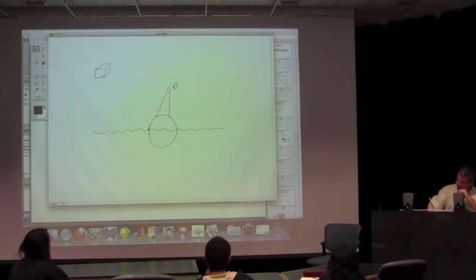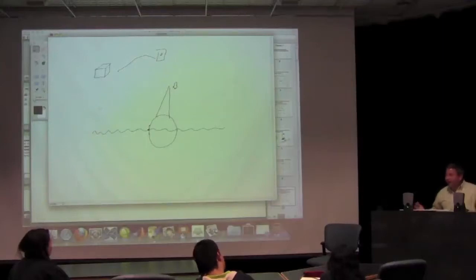And on the bottom of the styrofoam, there's a thermocouple glued to it. And then there's a wire that goes into the kayak and you hook it up to a voltmeter. And you measure the resistance. All right, great idea. You put this piece of styrofoam on the top of the water, it tips over, right? It goes up and down, it blows in the wind, and that's how we measure temperature of the surface. That's wrong. It's just not right.